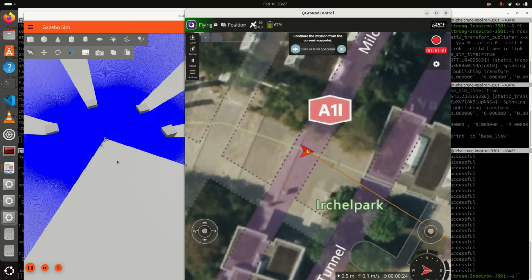We will turn on SLAM. We need to connect the map to the odometry, which is the job of SLAM. After you install the SLAM toolbox, you can launch it using this command. We are doing online SLAM, which is SLAM directly while things run, not recording everything and doing it offline. Then you need to use simulation time, because as I said, we need everything to be on the same timeline. When you hit run, okay, it seems to be running. Let's check with RViz.